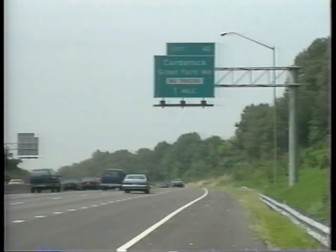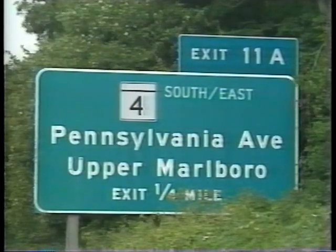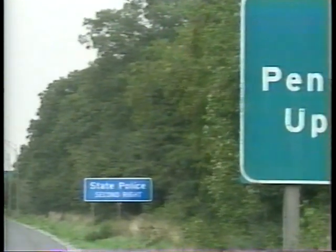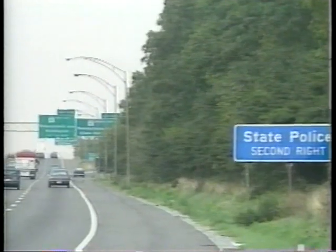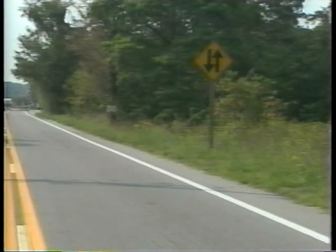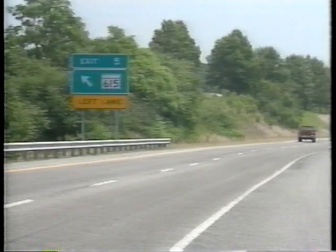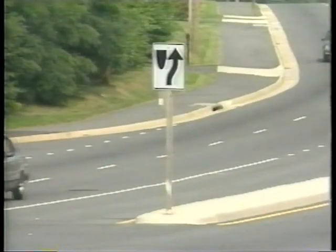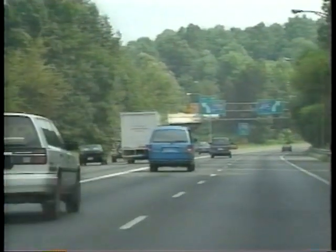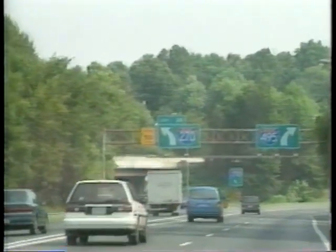It addresses a variety of applications. The rule here is that if a sign is legible and located properly, a driver traveling at normal speed will have adequate time to make a proper response. Generally, signs are placed on the right-hand side of the road, except for special cases like left-hand exits or for special emphasis, islands, and T intersections.